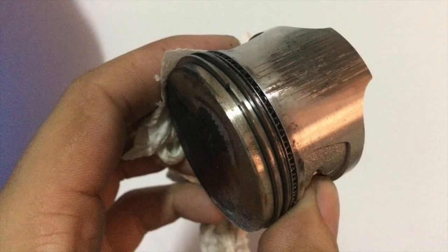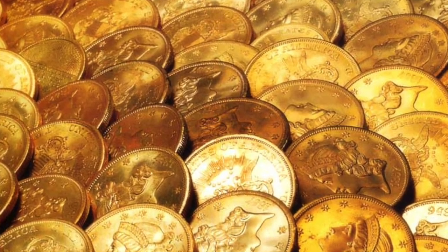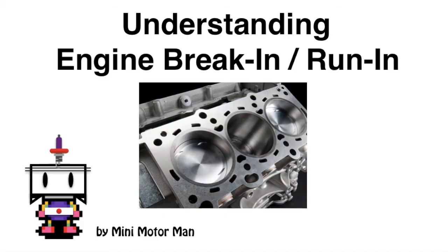So basically, because it's more cost-effective to do things the old way, there's still people who do things the old way, to keep costs down obviously, but that means you should still follow the old way of breaking it in, which is slow and steady wins the race, so to speak. So, in review, new vehicle or professionally rebuilt motor where the honing methods are state-of-the-art technology, you're safe to use the hard braking method. And it seems like that's what every manufacturer is doing these days.